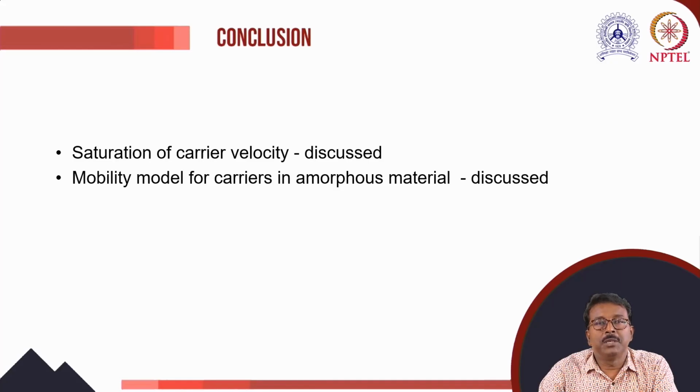To overcome this barrier, the thermionic emission model is considered, and to include this model with the multiple hopping or trap assisted hopping mechanism. Both types of mechanism may be combined in such materials, that is IGZO, GZO, AZO, etc. And for that we can use those models.